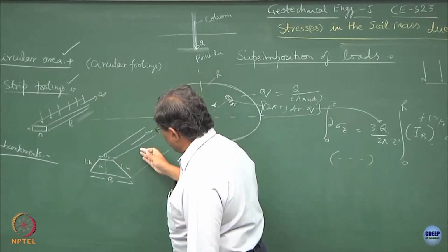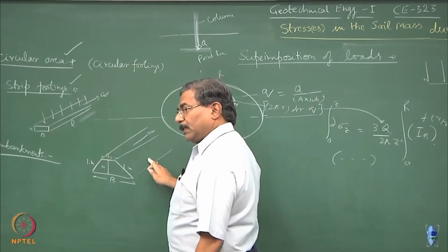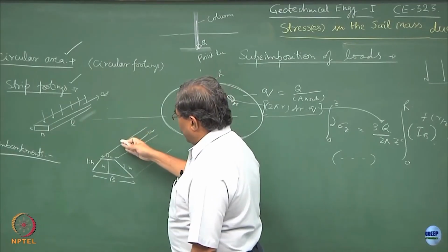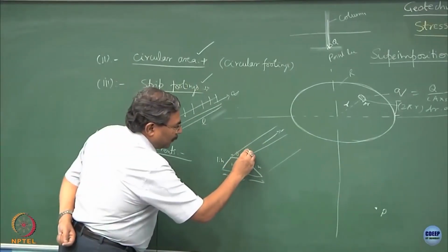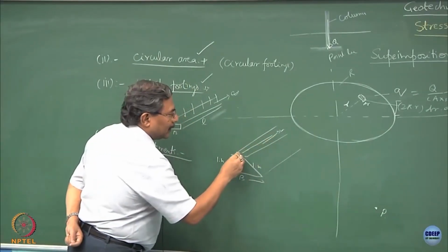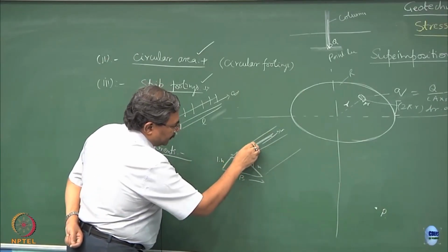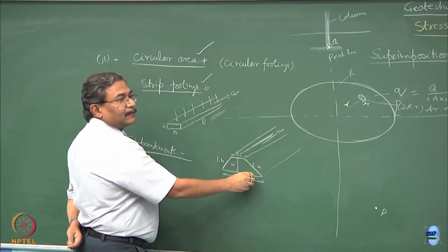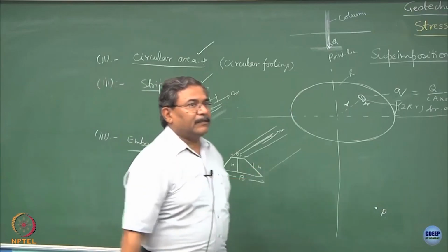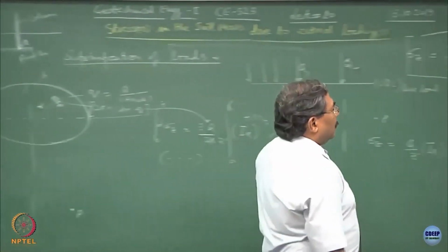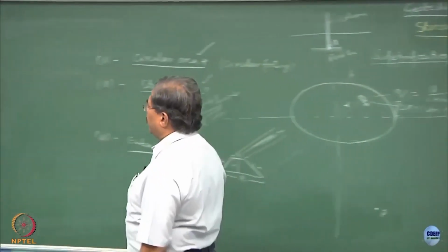So suppose I ask you to find out the state of stress at the bottom point, no problem, you can still model it. The entire loading can be, now there is a trick. The load is going to act over here, the railways are going to run over here, the roadways are here, aircraft loading is here. We have to delegate this stress at the base of the embankment. Clear? I use the word delegation. A better word for this is dispersion of the loading.